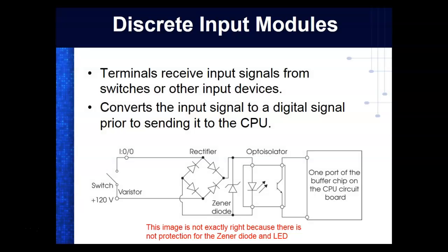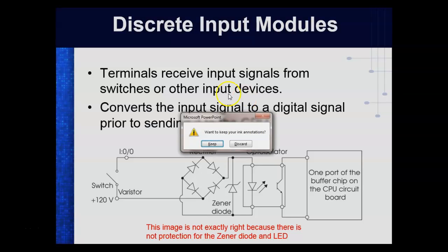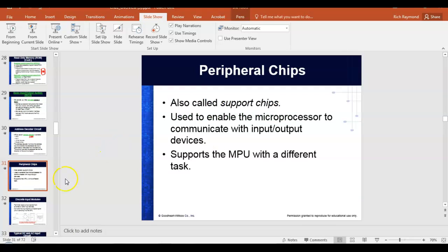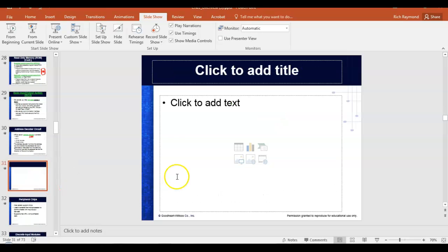This is when we hook up our inputs. And this is really important, and the book doesn't do a good job. I think it says one sentence somewhere later on. What we do is we don't hook our inputs in series. We can, but normally we'll come over here and we'll have our PLC.